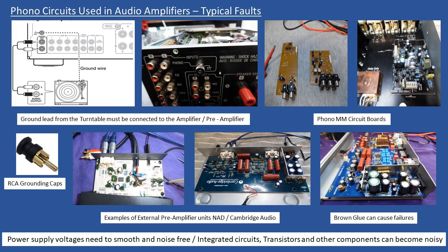In severe cases, you may even find that the brown glue has started to corrode or burn through the copper track. So again, just be aware of that. And then electrolytic capacitors can fail, so we hear this power hum, and then also the higher frequency capacitors.